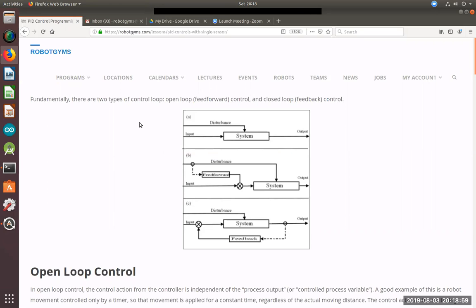So whatever state machine code you write now, say, for example, you want to move to one place. You write a code, put it in the state machine, and monitor how far you go, how many degrees you turn. When you reach your goal, say you move 3,000 steps, you immediately stop. But effectively, when a robot stops, you overshoot. When you turn, you overturn, right? But what if in a competition we need to stop at exactly 90 degrees? What should we do?